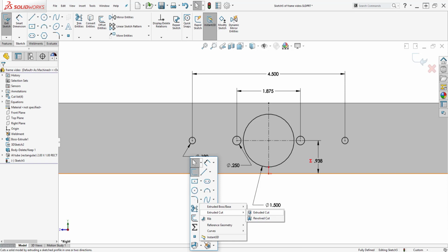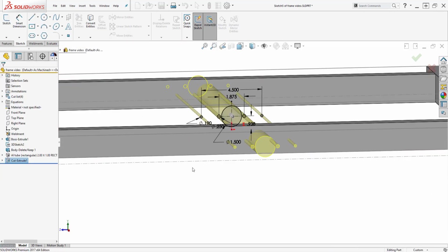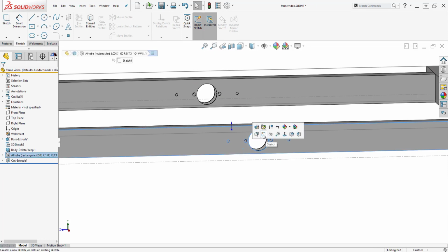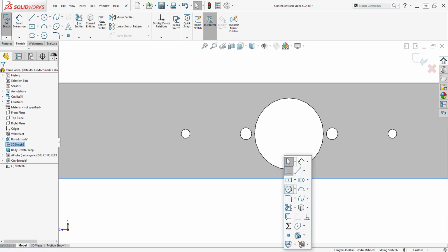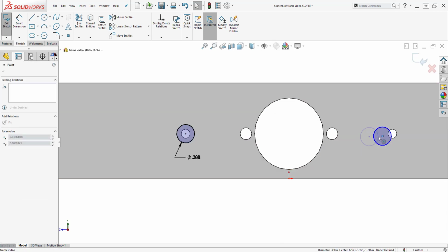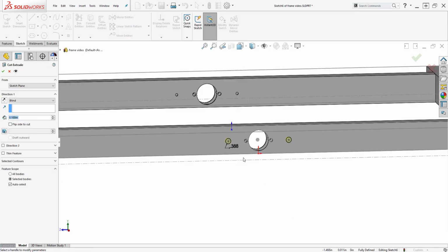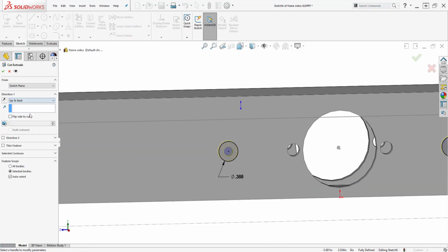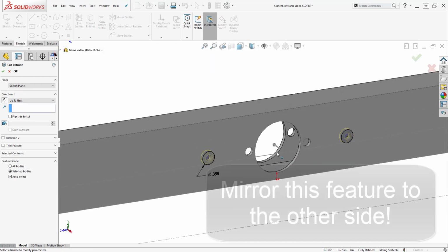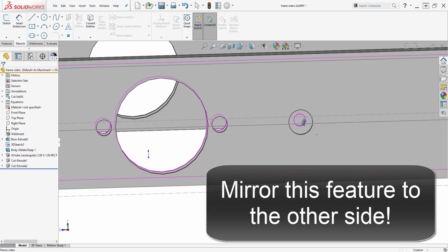For a 10-32 fastener, we use a .190 drilled through all, and then we bore the outside of the drive rail to a size like .388 that is large enough to let the bolt head pass through. This allows you to use the stock fastener from the gearbox kit without needing to buy fasteners an inch longer. If you mess this up, you can always insert a washer into the tube from the 1.5 inch flange hole, but that's a pain to do. I don't recommend doing that.